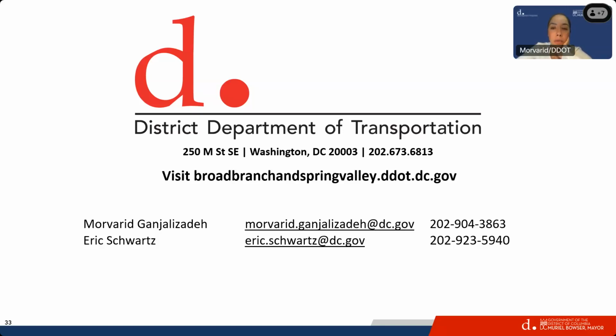We've been told that there are some schools and churches or upcoming projects that are coming. So after talking to the ANC about those areas, we are planning to either shift them, or we also shorten some of them already. We've broken some of them into pieces already, as Mike mentioned in the slides, to provide more parking spaces. I'm also going to add that the bioretention cannot be longer than 70 feet. I know that you see 115, 120. We're working on breaking them into pieces that are not longer than 70 feet, so we have a path walk around it, or maybe just provide one parking space in between. We consider the parking space as much as we could.